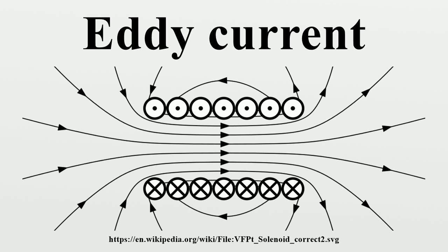In contrast, at the trailing edge, the clockwise current causes a magnetic field pointed down, in the same direction as the magnet's field, creating an attractive force between the sheet and the trailing edge of the magnet. Both of these forces oppose the motion of the sheet. The kinetic energy which is consumed overcoming this drag force is dissipated as heat by the currents flowing through the resistance of the metal, so the metal gets warm under the magnet.